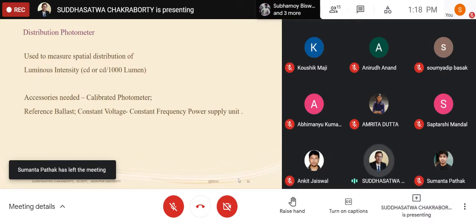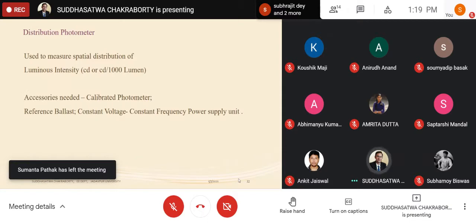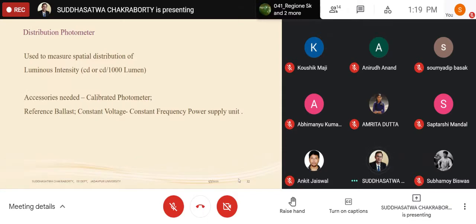So in this way, no matter what type of luminaires we are dealing with, based on the application, indoor or outdoor, we are going to measure the intensity value at two different angles. That's why the 2D matrix I was talking about will be the input for all of you who are going to calculate the luminous flux using the zonal lumen method. At each zone we can calculate, and that part I will show you later on. That is a very simple method which can be adopted.